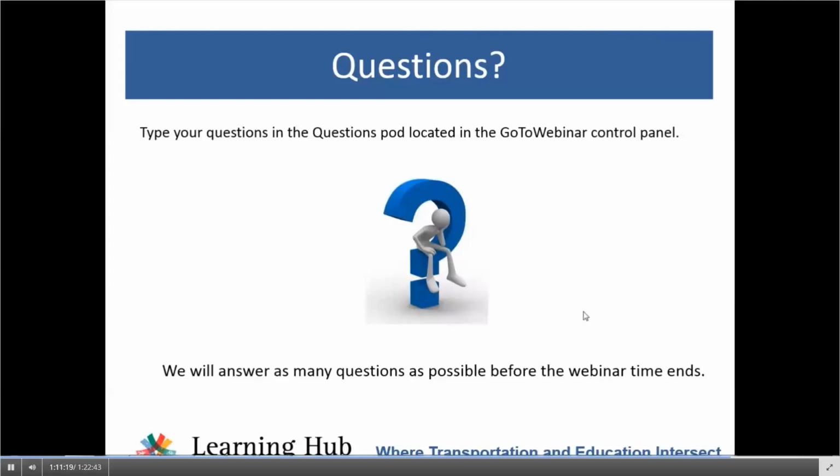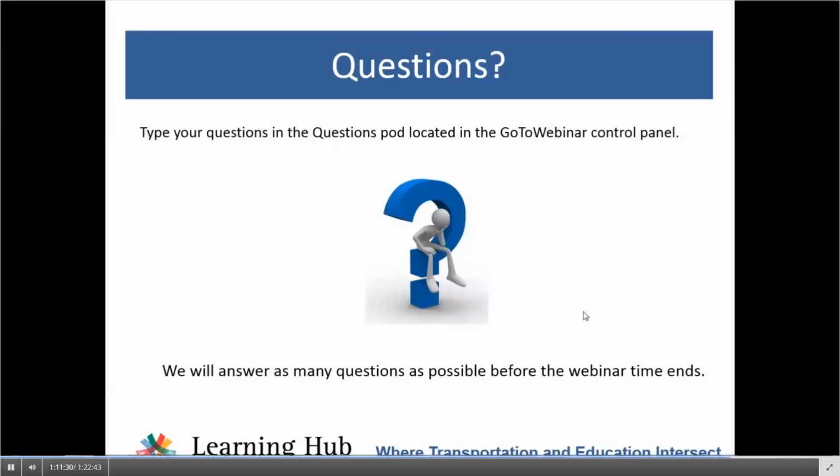The guide takes the position that we want to provide you with a range of performance measures, and you can decide what's the most appropriate measures to include as part of your analysis. In many of the cases, for urban street facilities or freeway facilities, if you're looking at extended length of facility, you're getting average speed and travel time as key performance measures that are coming out of the analysis.